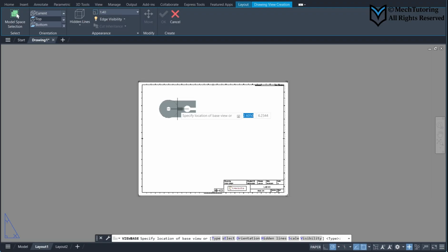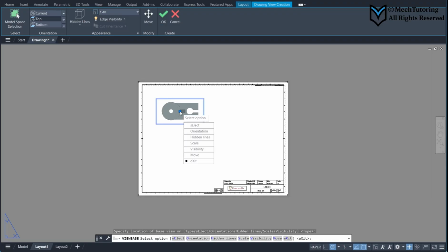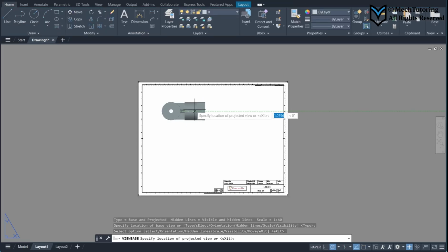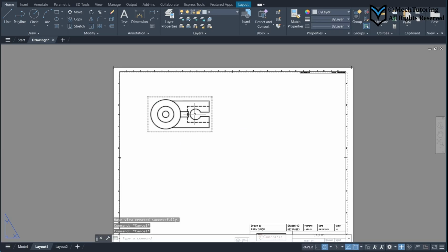In case your view is not properly orientated, the top is going to be top, but it's not going to be the same way you see over here, okay. So you're just going to click and press enter and press enter again. Don't drag on either side over there. You can stay wherever you are or even drag, doesn't matter, but press enter. Don't click on the screen, okay? It's going to show you the view. That's the top view you want.